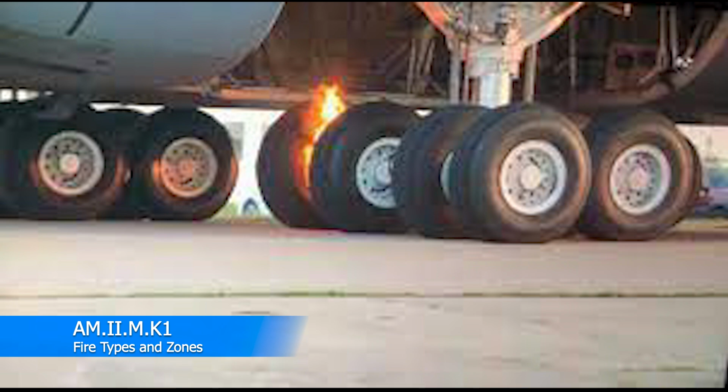Then the other aspect of it is that you have an immense amount of heat on those aircraft brakes. You notice that you have a fire coming up between two aircraft right here, on what I believe is a C-5 and maybe a C-17, and that fire is going to be started because of the aircraft brakes. They simply get too hot, some debris gets in there, it lights off. Once you get a fire going enough, it'll jump to the tire, and now you have a tire on fire, and those tires will burn pretty hot. You have a lot of tire right there next to them. So once it gets going, it's just going to keep on going, and you're going to end up having a problem really quickly. So that's something to keep in mind, that you could potentially have fires inside of the wheel well.